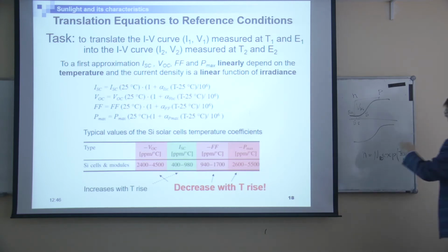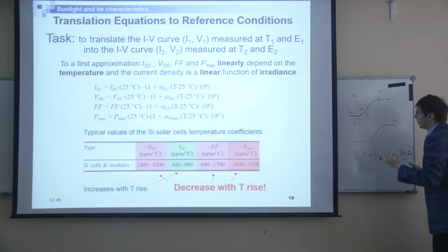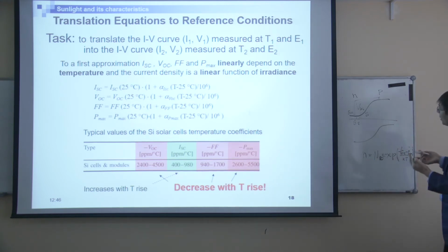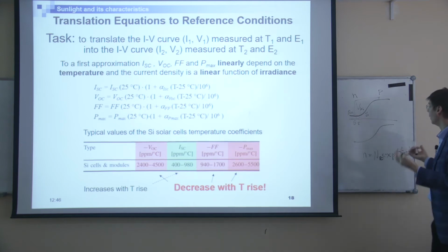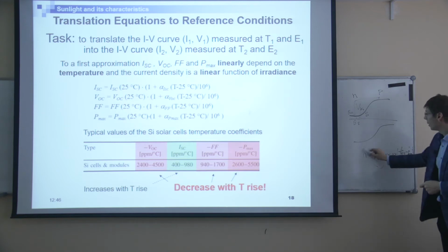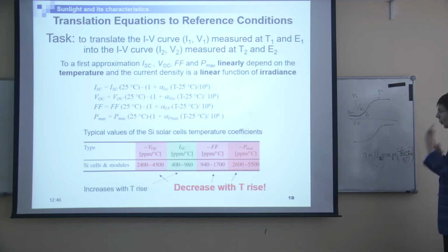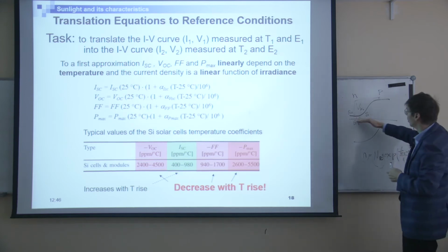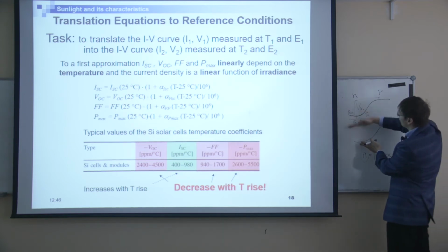So this concentration is related to the doping density, which is not changed. It changes with temperature, but the change is quite small compared to this exponential behavior. Temperature is changed, this factor is not changed. So there is only one way: the position of the Fermi level should change. So it goes toward mid gap.